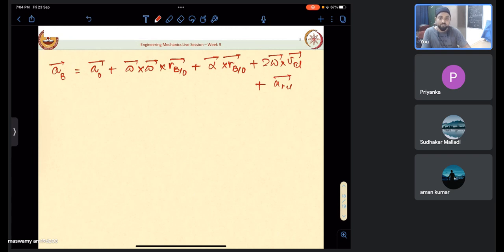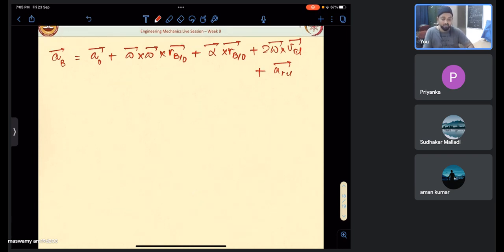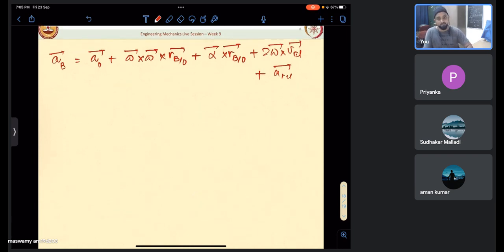So you see, when we are given relative quantities, because from the construction of that cannon, the construction will have a compression spring, which will release its energy, and the ball will be shot out. So we only know its velocity relative to the barrel, and the barrel itself is moving. So ultimately, we have to calculate the absolute quantities. This is why rotating frame of reference analysis is important, because generally we only get relative quantities.